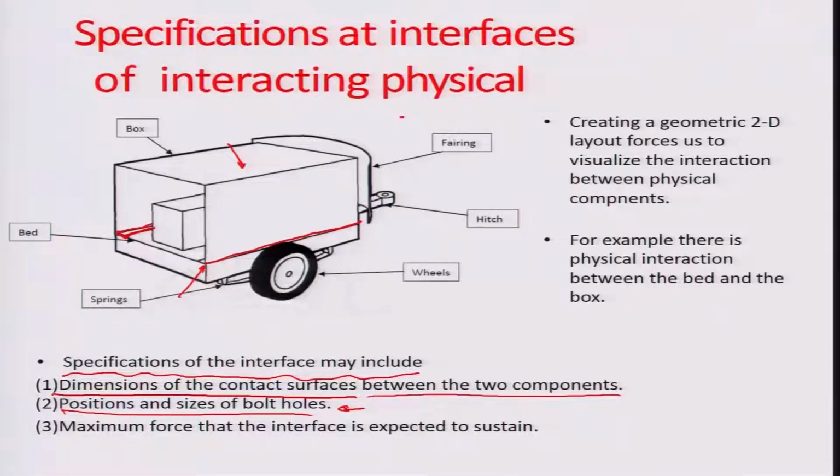And so, you have to design the interface in a manner in the configuration, so that it can sustain the maximum force that is expected to be sustained at such an interface. So, in that manner the configuration has to be planned. If need be, some structural stiffeners or some other additional engineering design improvements can be made at the interface at the configuration stage itself, so that there are not many problems associated with the component later.